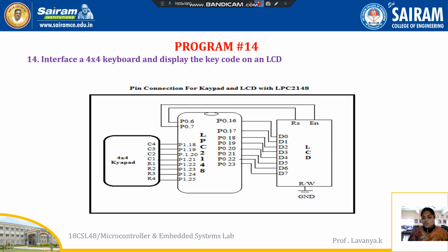So all the data is interconnected to our LPC 2148. Before that, our RS register, that is the register selection pin, and the enable pin must always be made high, and only then can we see our output on the LCD kit.